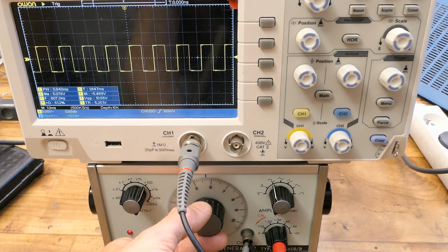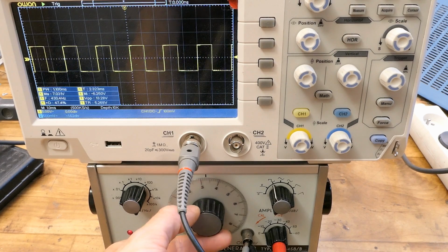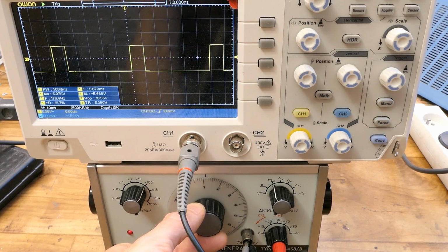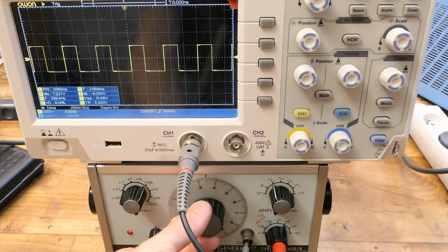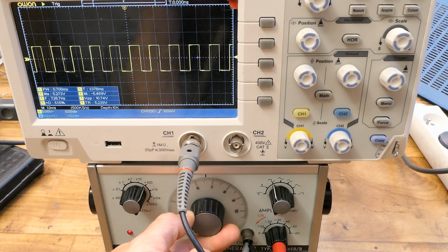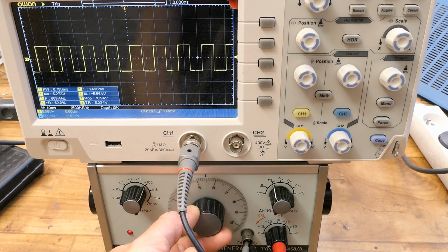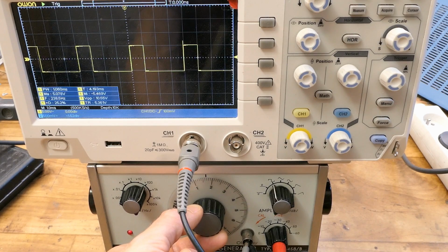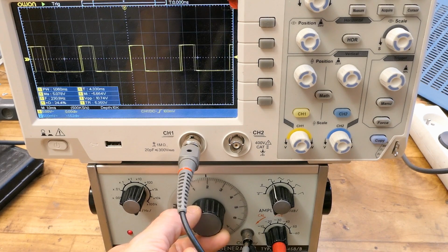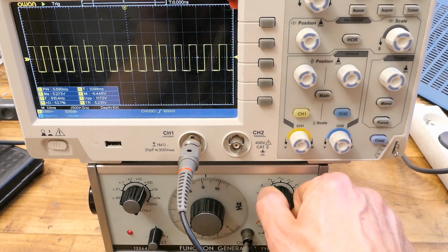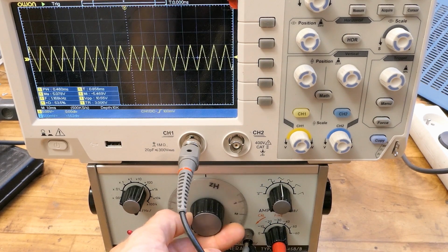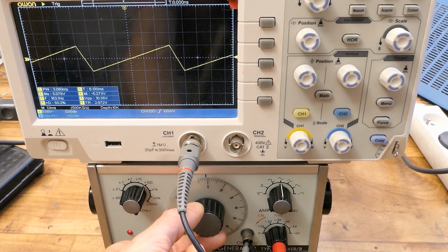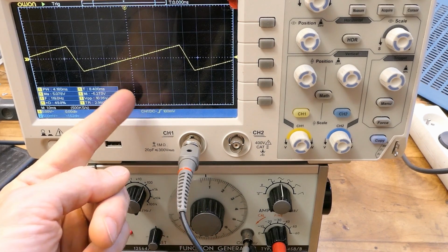When I reduce the frequency, it's reducing nicely all the way to 5, and then something strange happens. It's increasing only the off time, not the on time. You can see here it's changing both times equally, it's 50% duty cycle, but from some point on it suddenly increases just the off time, not the on time, which is weird. And for the sawtooth, it works in the upper range as well, and when I go down, it suddenly increases the length of just the rising part, not the falling part.